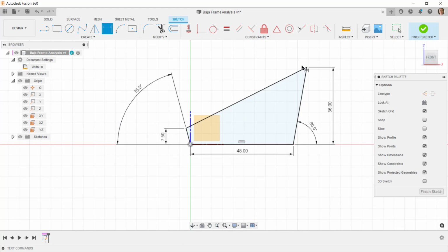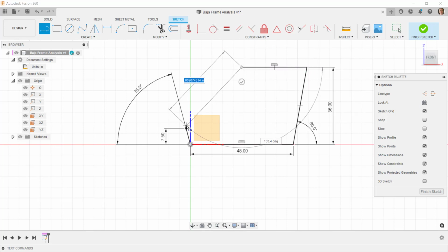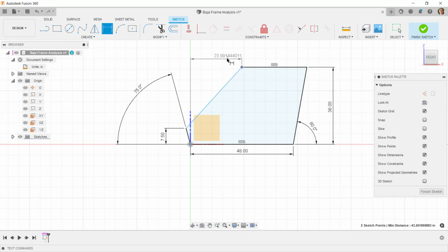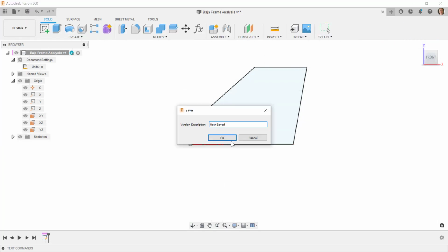And I accidentally left out a line up here that I intended, so I'm going to delete this line, and we'll put it back in again. So I'll delete that line and I'll come over horizontally. That's the line I left out, and then I'll come down to here. I'll then dimension from the origin to this point, that horizontal distance is 30. Notice that the sketch turns black. It's all fully defined. I'll click finish sketch and I'll save my part.